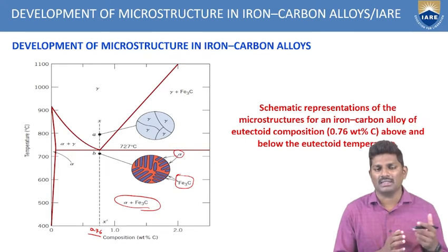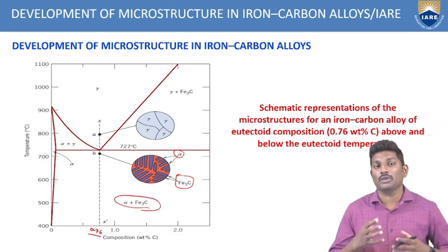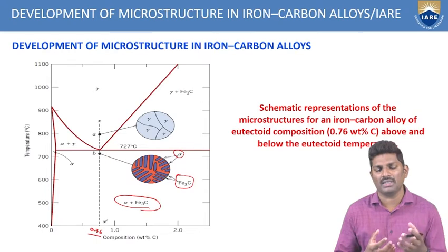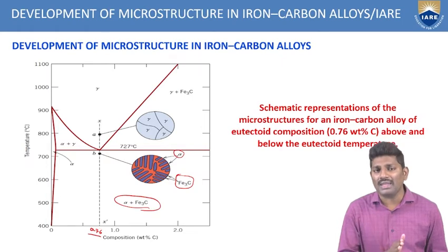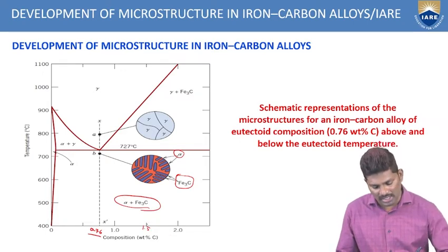So like that you are getting changes or developments in the microstructure when you cool the material. Any type of material, when you once heat it and let it cool for some time, what is happening? During this cooling process, there are a lot of changes in the microstructure. Since we are considering 0.76 percentage, 0.768 percentage of carbon, at that point only we are getting these points. Suppose you increase the percentage again, suppose 1.58 percentage, then you have to draw a dotted line again